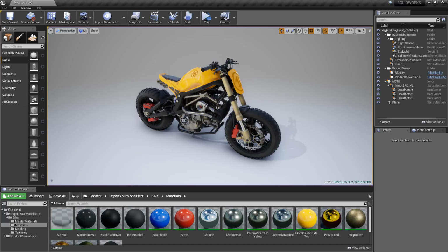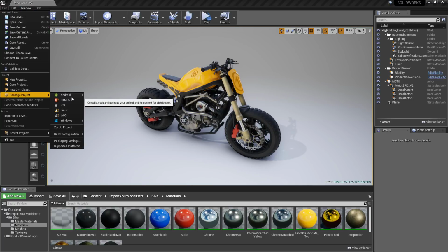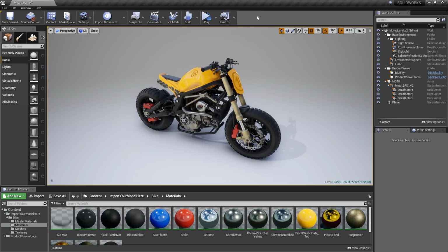We've brought in some CAD data, and all we're doing is packaging that out very simply, like I've just shown there. We would simply go to File, Package Project, and you would select to where you want this to go. If you're going to something like a Mac format, or a different format, you can simply do that. In this case, I just went to Windows 64-bit, and it's a shareable standalone application that launches as its own VR app. And this is an excellent way to experience that data or share your experience of your CAD design with anyone at that point.